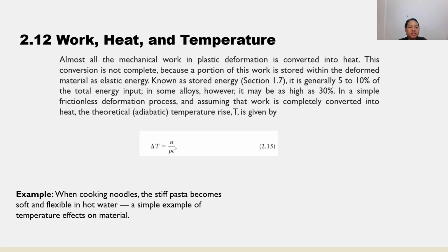In a simple frictionless deformation process, and assuming that work is completely converted into heat, the theoretical adiabatic temperature rise ΔT is given by ΔT = u / ρC. These effects are critical in manufacturing operations, where heat management determines not only material response, but also tool wear and energy efficiency. Balancing this factor ensures quality products and process stability.